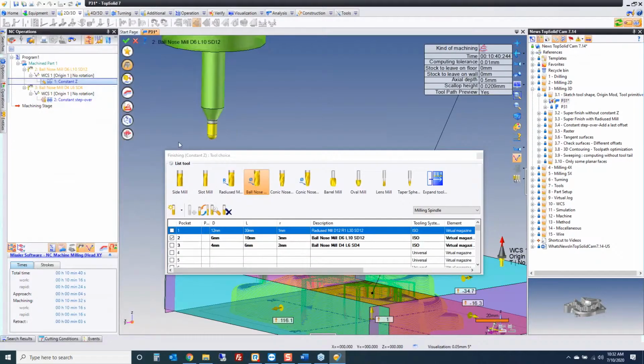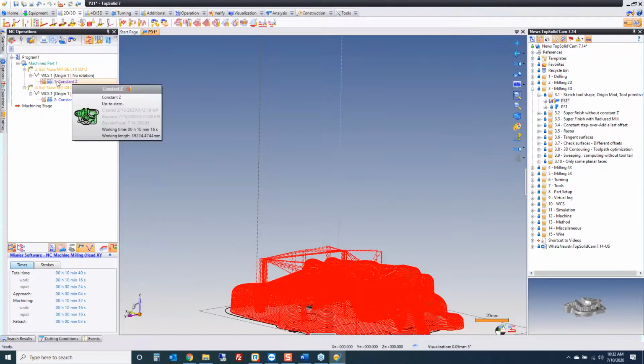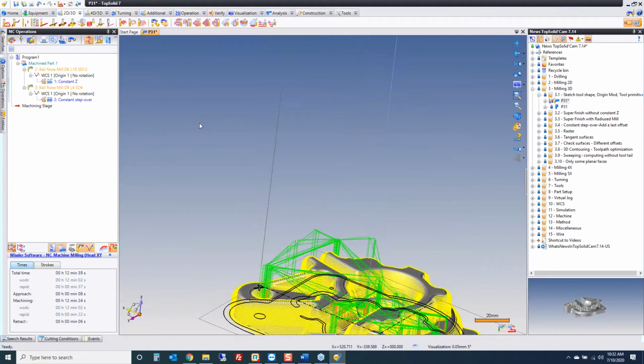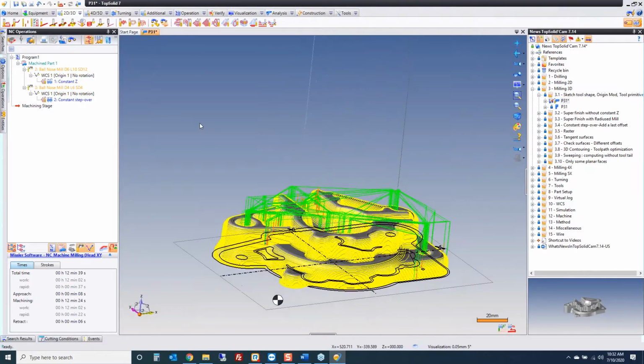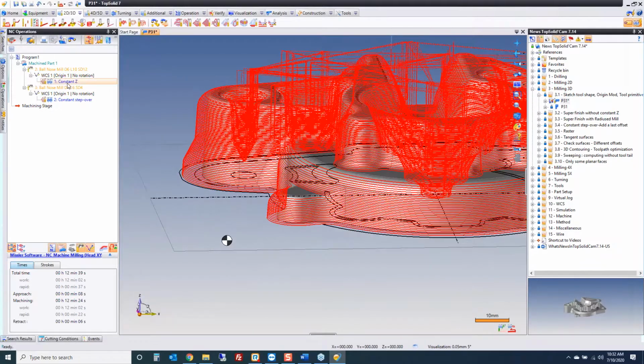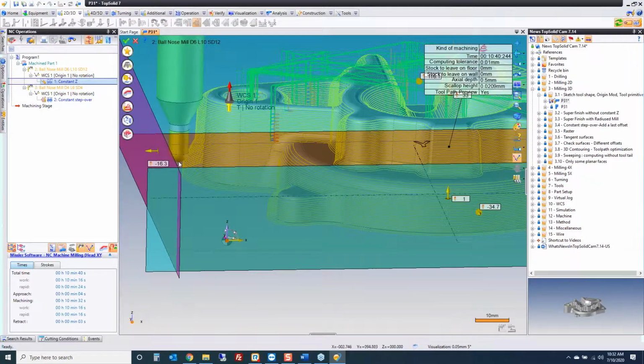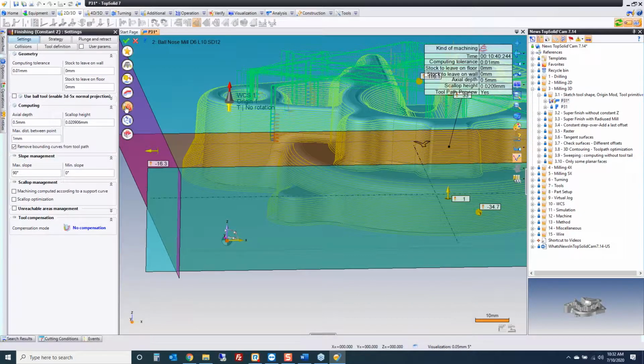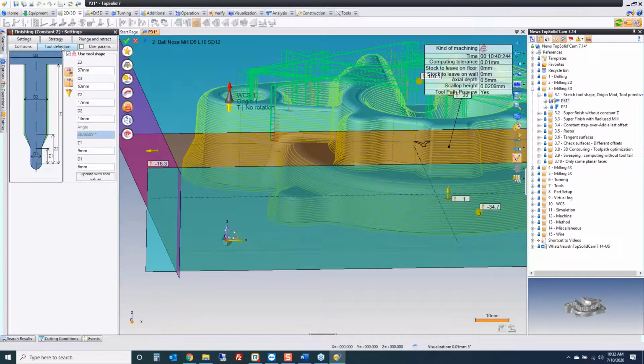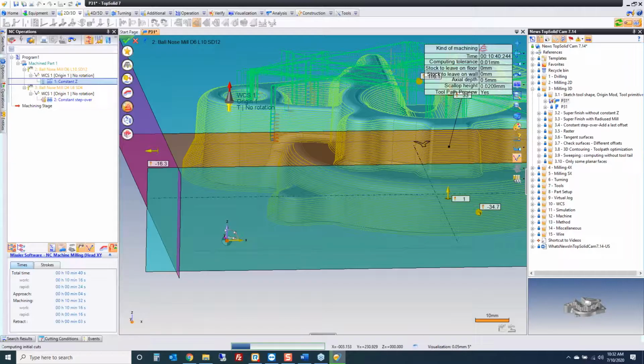In this first sample, I'm using this new tool primitive. Let me flip this around, and you can see that that tool primitive is avoiding running the shank of the cutter into the part. So that's kind of cool. How does it work? If I go into settings and I go to tool definition here, you definitely want to click on use tool shape. And if I update this with the real values of the tool, and we click OK, let's let this crunch out once here.